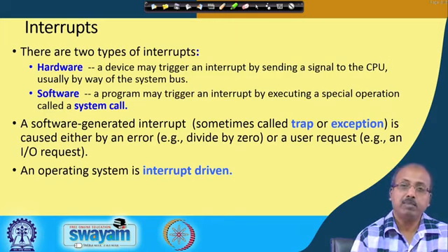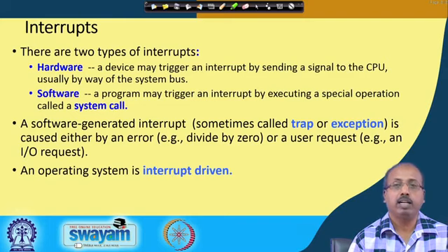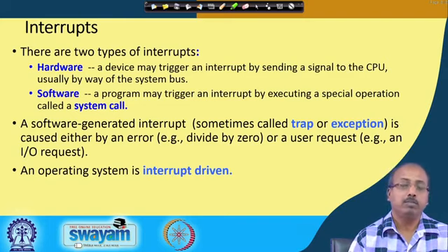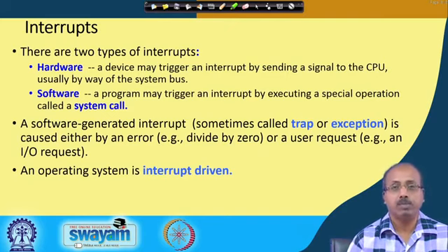Now, if the system is designed so that the processor checks whether the user has pressed some key or not, and waits for that, then it becomes clumsy, because the processor is waiting unnecessarily for a long amount of time. One solution is that the processor may be doing something and periodically comes back to check whether the user has pressed any key.